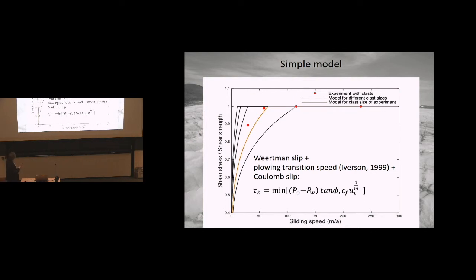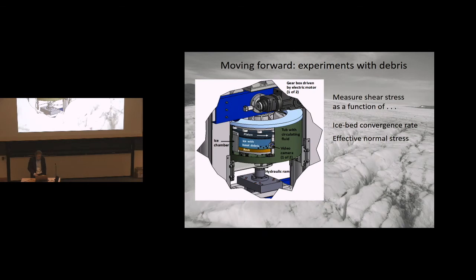And then the transition speed was simply given by this model. So this is the constitutive rule we would argue is relevant to ice sitting on a soft bed, bearing in mind that just about everybody who's done this has treated the till like a viscous material. That's not universally true, but it's usually been true.